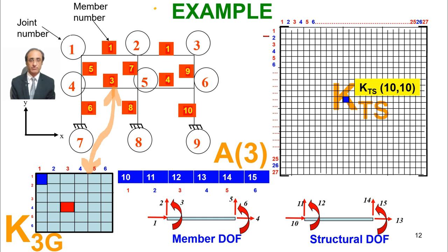Where will K4,3 go? 13 and 12. Right? It will go to 13 this side and 12 is here. So similarly, we know where each element goes, when we say a particular element of this is some of the elements of the stiffness matrix in global coordinates of the members forming in that particular joint and having the corresponding degrees of freedom. So now we can do it.